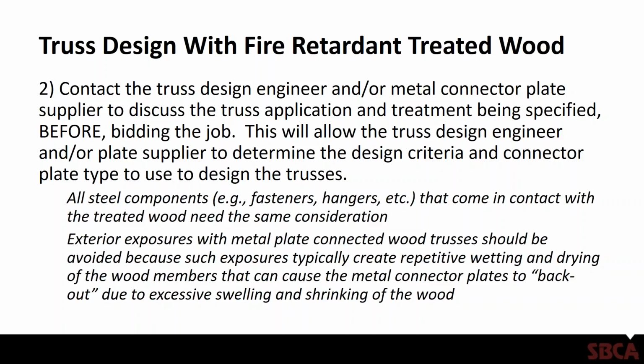And they ideally would discuss the truss application and treatment being specified before bidding the job. This allows a truss design engineer and/or plate supplier to determine the design criteria and connector plate type to use to design the trusses.